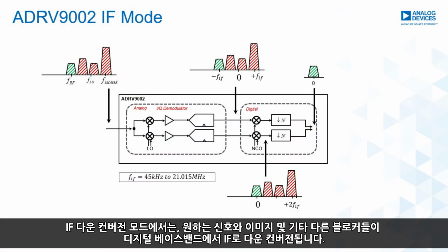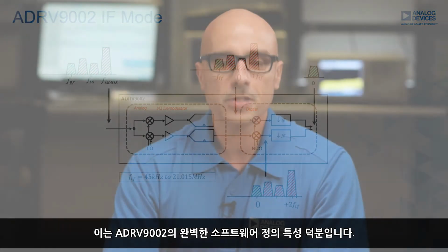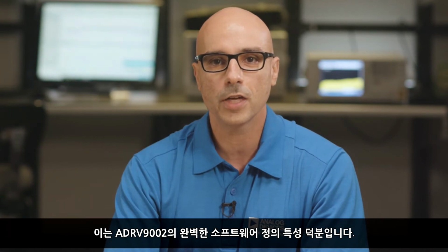In an IF down conversion mode, the desired signal, its image, and any other blockers are down converted to an IF in the digital baseband. The desired signal is extracted, the blockers are filtered, and the image is rejected, all in the digital domain. This is thanks to the true software-defined nature of the ADRV9002.